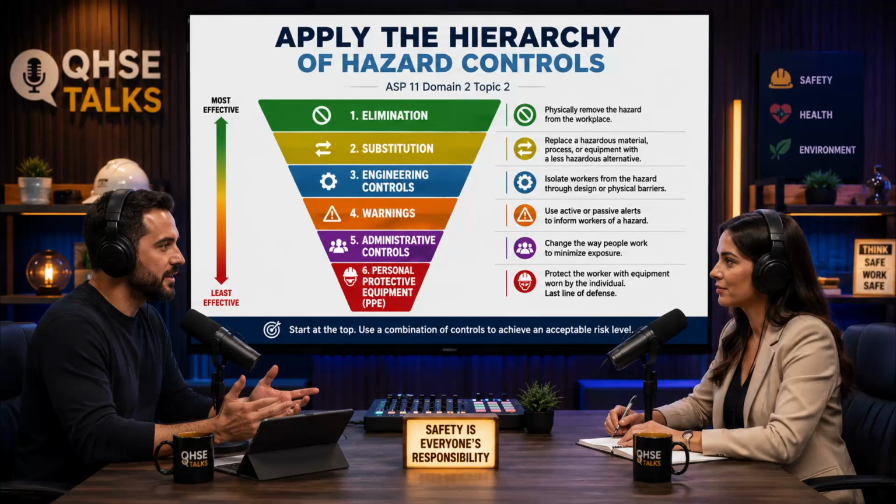Okay. The scenario involves a hot works operation, specifically brazing. Now, brazing requires an open flame and generates extremely high heat to join metals together, right? Yes. And in this scenario, the brazing operation is currently taking place inside a combustible dust environment.